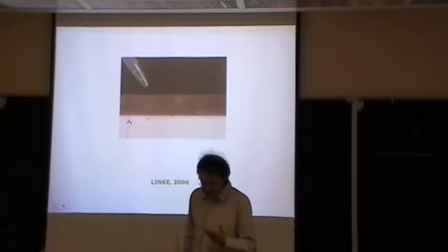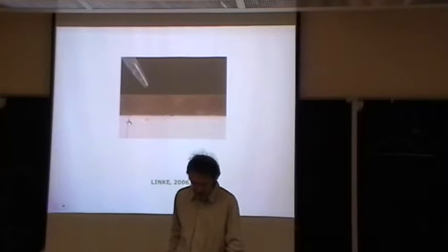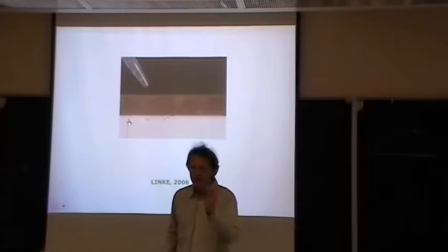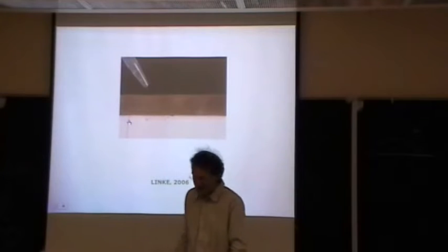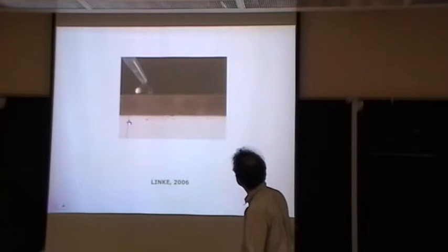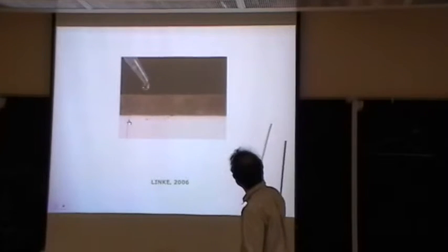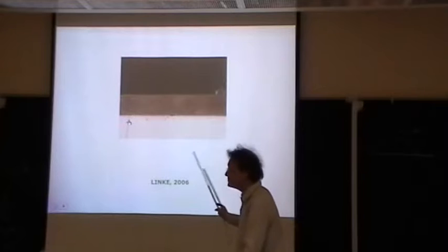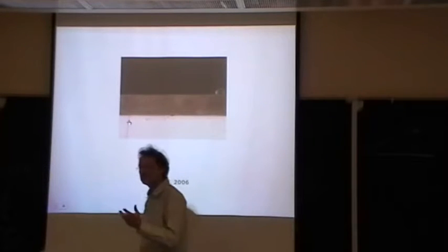However, he made this experiment where you have a solid, let's say at 300 degrees, you place a drop of water, and you look from the side. This is real time, and you see that these drops are all going in the same way, all at the same speed. This speed is quite quick, about 10 centimeters per second, and this is, of course, a direct illustration of something that I said yesterday: in this highly non-wetting situation, even a very small force is enough to induce quite a large velocity, because there is very, very little friction.